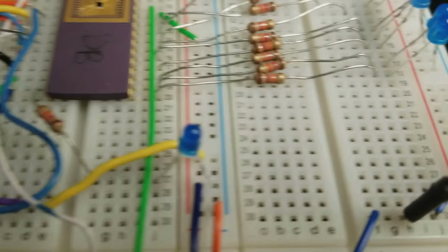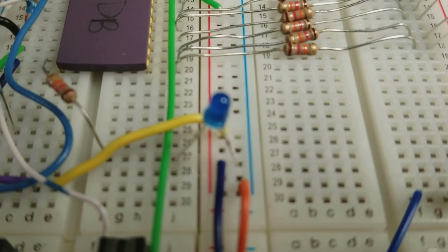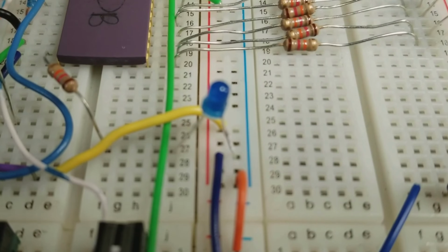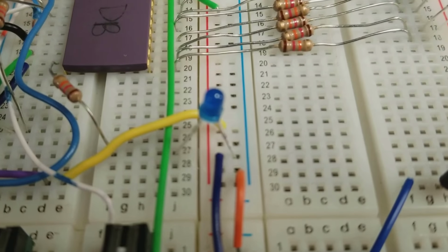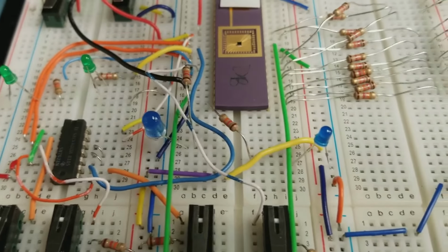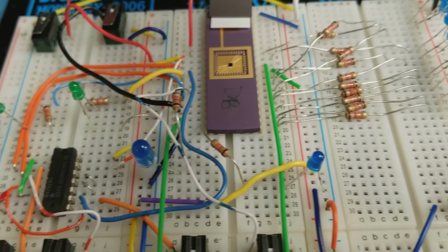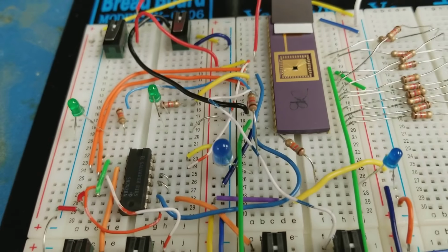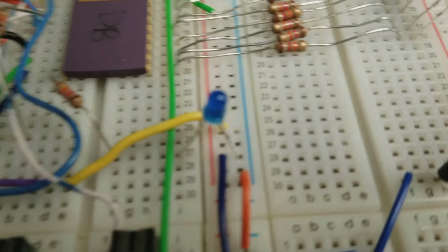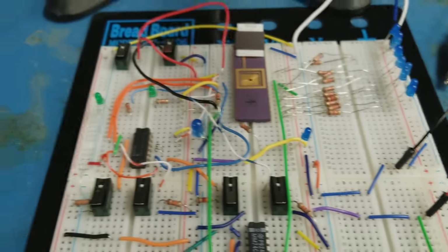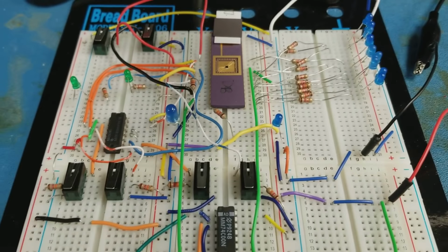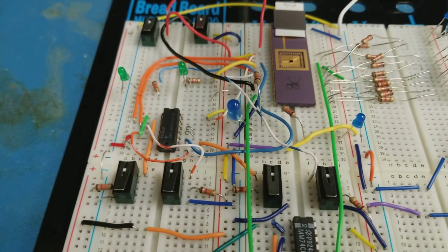Right here, this LED is used to say, okay, should we show the game board or not? Because in Whack-A-Mole, typically you have like 6 or 8 moles, and the pseudo-random number generator that's inside of there, it's a linear feedback shift register. It can have a certain state that it wants to output. However, this is used to say, okay, we know where the placement should be, but we don't want to show it for this one. And then right here is our start button. Whenever I hold this down and the clock is running, the things will light up and it'll start showing the states. It'll start showing the placement.